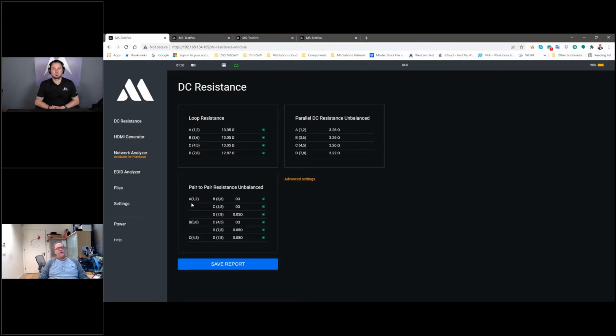This is actually showing us the differentiation between pair A, for example, and pair B. It shows us, and this will also affect these numbers, that if the cable is unbalanced, it will be reflected in voltage drop, but it will also be reflected in the propagation of the signal through the category cable. On LAN, if we have a bad type of cable, meaning there is differentiation, it will fail at some point or another. This will affect the bandwidth that you are achieving.